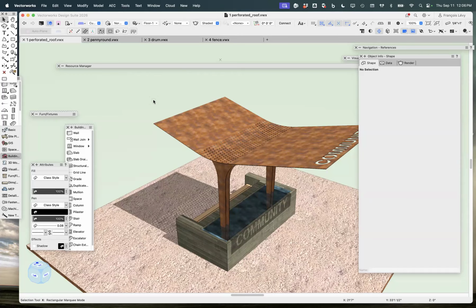And then when I get to the edge, I can tell the array whether I want to overlap the edge or trim it to the edge. If it overlaps the edge, then the array is just going to go all the way over the edge, or trim, so it's going to snip off any of those arrayed items right when they get to the edge. And then since it's a subtraction, when I exit this subtraction, it'll take a moment to calculate.